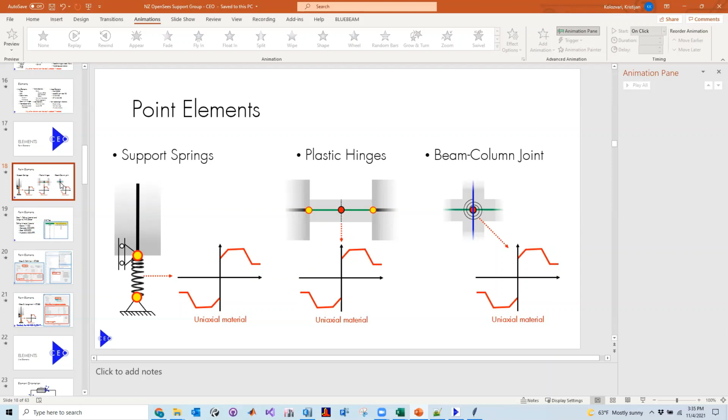So the reason I'm asking is, as you said, the industry is demanding more nonlinear analysis. It's also demanding to include more of the soil structure interactions and all those things, right? The way I've seen so far, most of the time soil structure interaction is just using some kind of springs at the base. It's nothing super sophisticated. So I was just curious if there is a trick to implement that too in this.